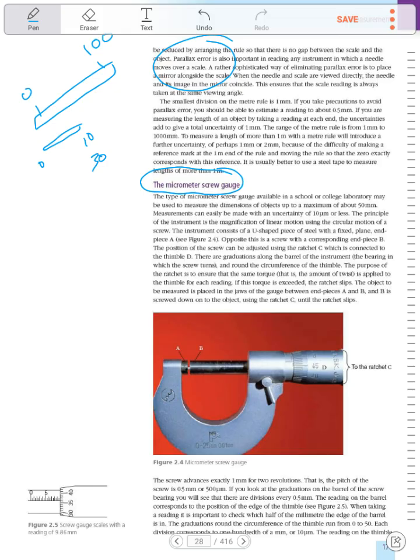In the micrometer, at the beginning, you have to check zero error. Zero error means that the horizontal line here, this one, has to be parallel or in line with 0 on this movable screw, okay? Now, if you have a reading after you put the object between these points, if you want to find the diameter of a small ball, you have a reading like this.